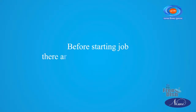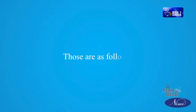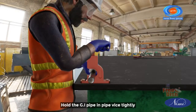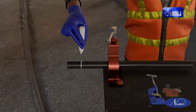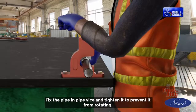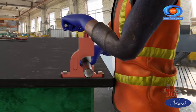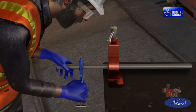Before starting the job, there are some preliminary checks to be made. Those are as follows. Hold the GI pipe in pipe vise tightly. Mark the required length as per drawing. Fix the pipe in pipe vise and tighten it to prevent it from rotating. Fix the pipe cutter on the GI pipe.